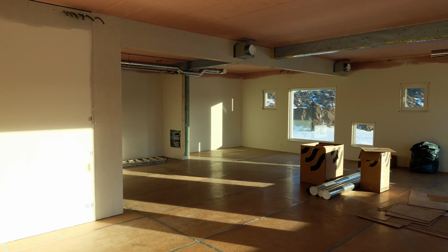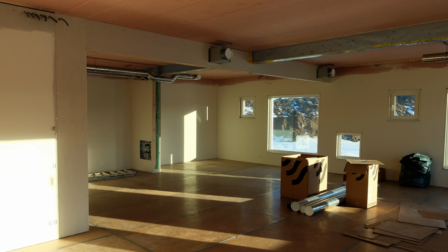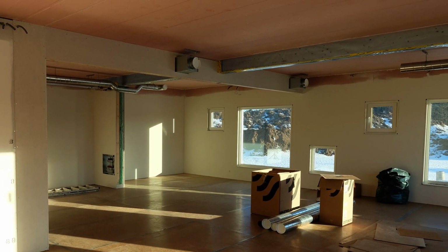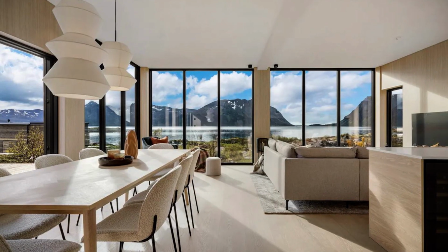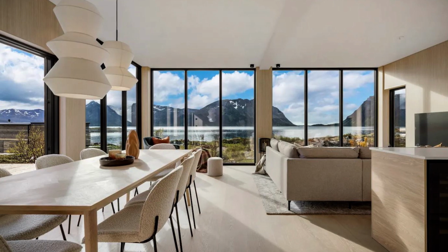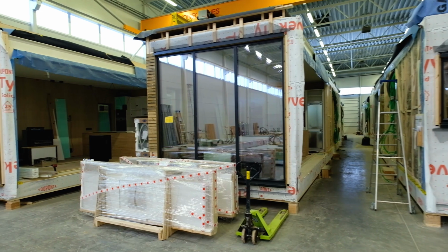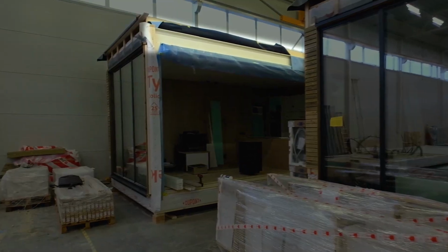When large spaces are desired, modules can be placed side by side, where the longer sides of such elements are left open. Normally, an element with large open sides would lose the required stability. Therefore, strong frames made of steel or engineered wood are installed in the construction of such volumetric elements to help maintain shape and ensure stability. A similar situation can also arise if, architecturally, the building is provided with openings covering a large part of the external wall, in which case the steel frame is integrated into the external wall of the module.